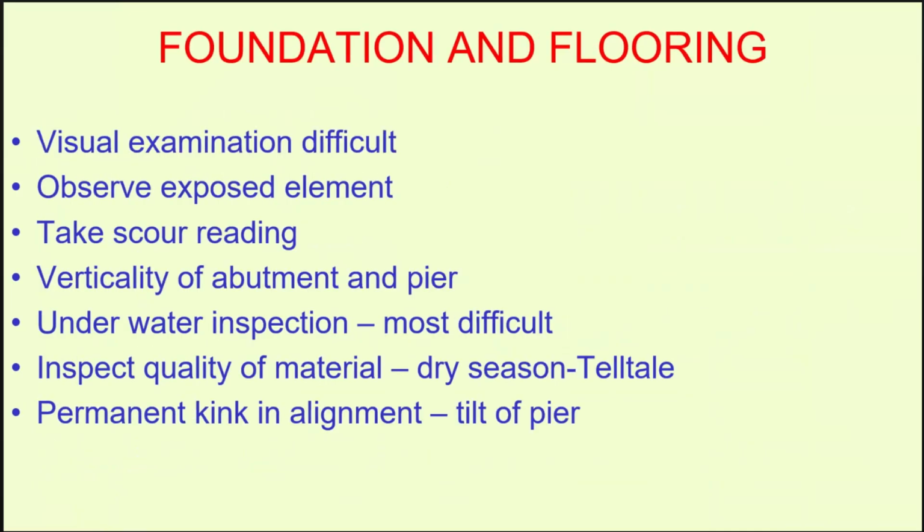In case of foundation and flooring, visual examination is difficult because it might be covered with muck. Observe exposed elements, take a scour reading, and check verticality of abutment and pier. Underwater inspection of the foundation is slightly difficult.